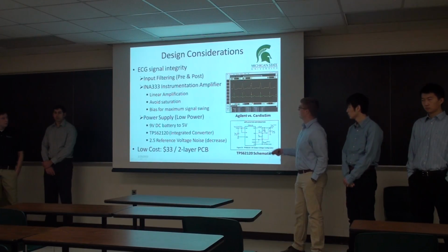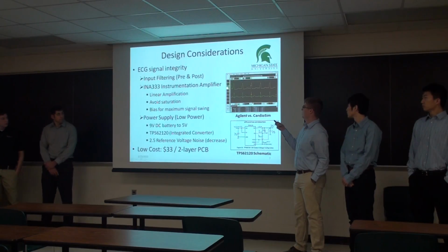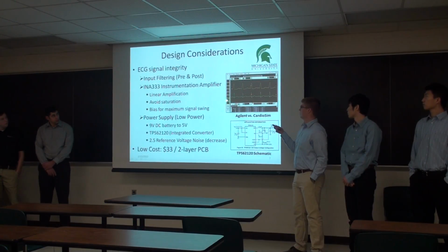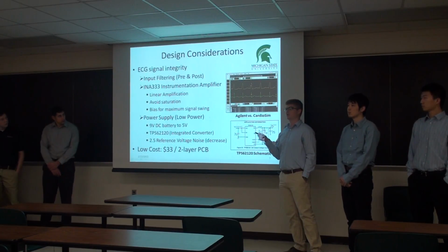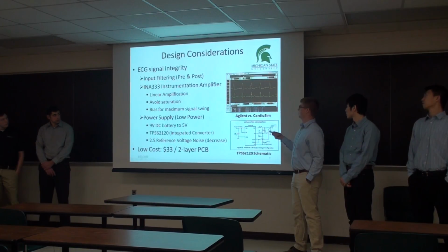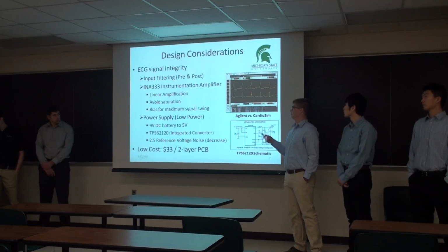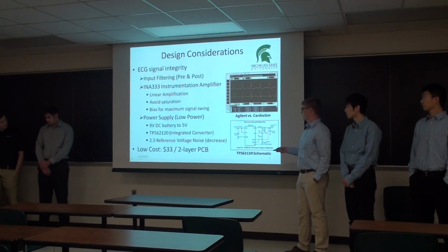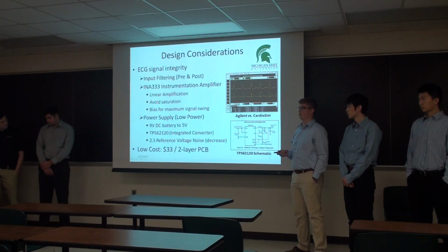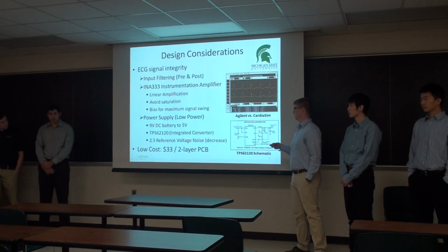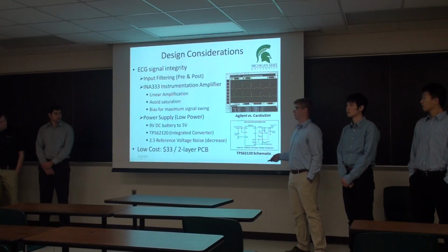To ultimately get the best result on our output signal. Shown here on this figure is an example that we've already filtered from our CardioSim, and we're comparing it to the Agilent signal generator cardiac waveform. As you can see, there are some differences. The Agilent signal is much more precise. And the buck converter that we're using on our first board design is the TPS62120, and the application note from TI's website helped us design our buck converter circuit.